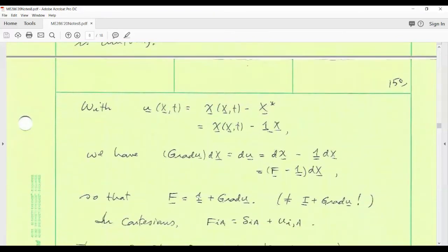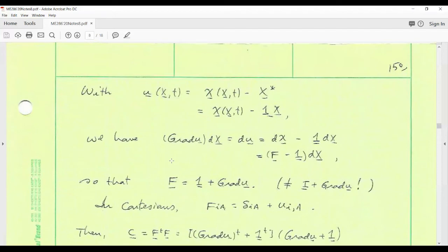So that's important. So we have our displacement finally defined here in a mathematically consistent way. x star is a shifted version of x. We can use the chain rule to compute the referential displacement gradient. I'll use capital G for the referential gradient, capital Grad u, operating on dX is du by the chain rule.